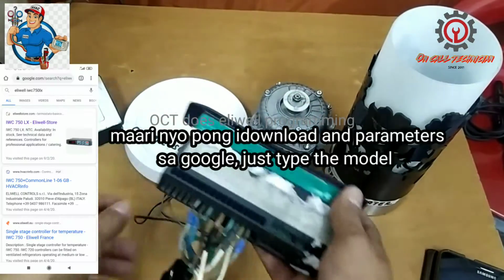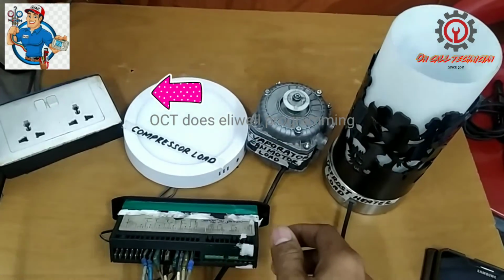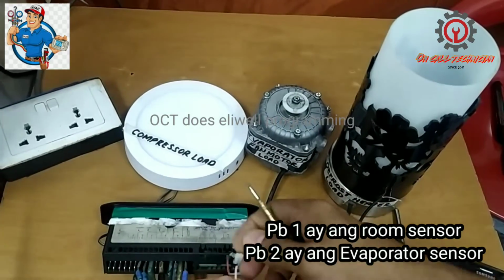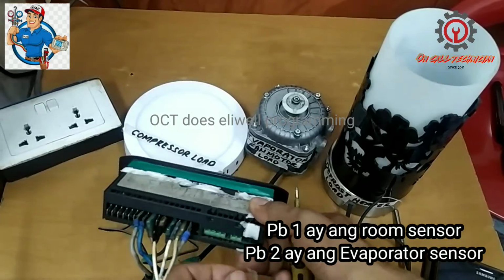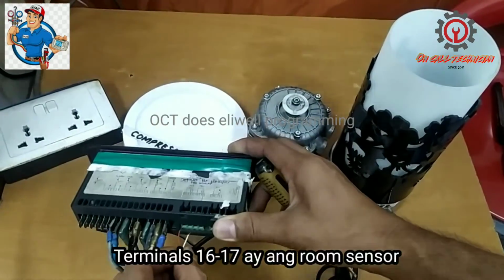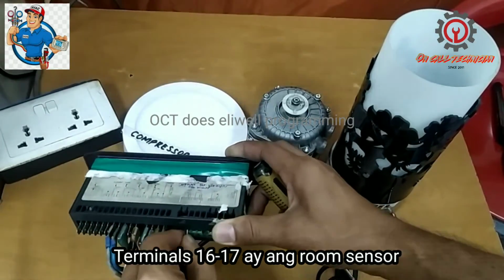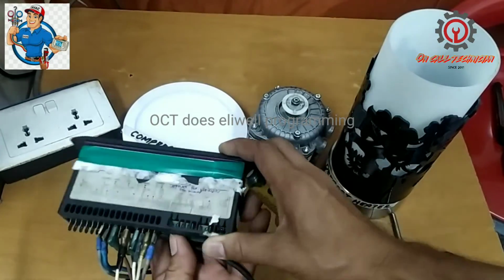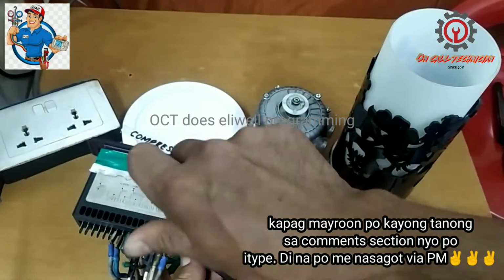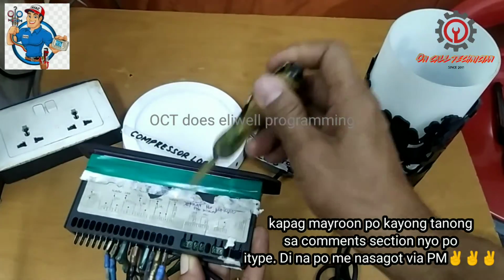Okay, now that we have a load, we're going to install a sensor. Okay, this one I'm going to put to the PB1, which is the room sensor. I'm going to plug into the terminal 16 and 17, which is the slot for the room sensor. Papasok po siya sa terminal 16 at 17.